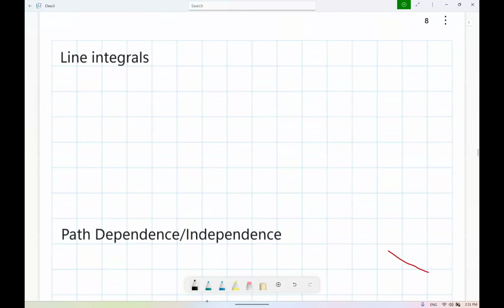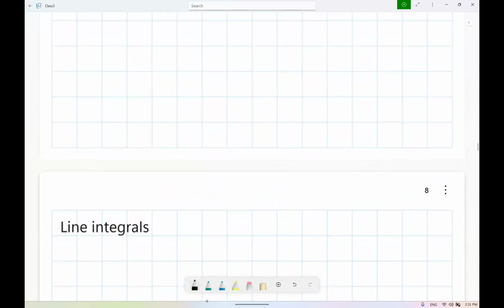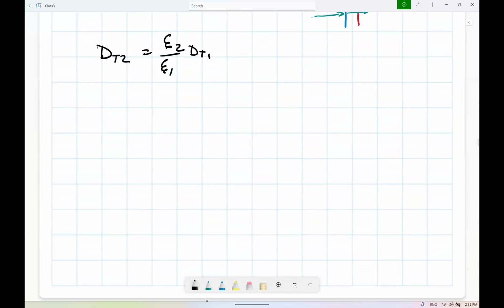Like when there are corners in a geometry, it is generally said that charges are more concentrated in the corners than the rest of the surface. So how can we, in this general study, just say that charges are uniformly distributed? Well, that's the thing. That's why we don't do analytical solutions and we do finite elements. You're right.